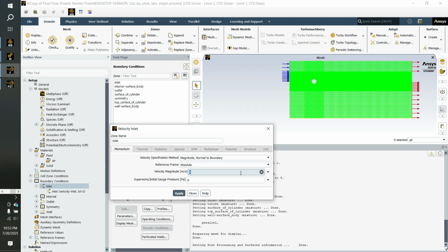Okay, so when we did turbulent flow, 8 meters per second correlated to a Reynolds number of 533,333.33333, which is greater than 500,000, resulting in turbulent flow. So if we half that to 4 meters per second, then it would be less than 500,000 and will be laminar flow.